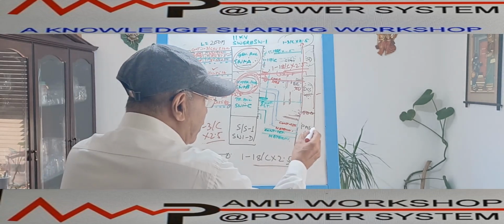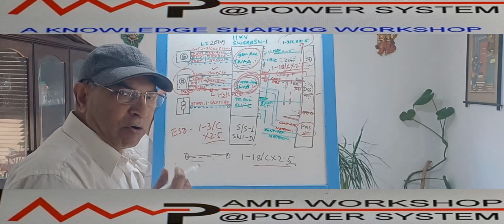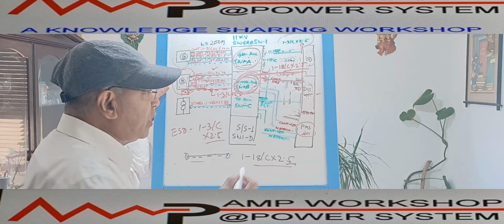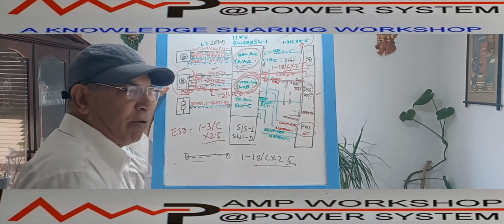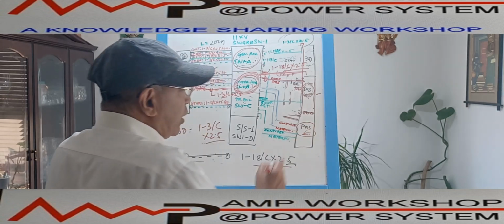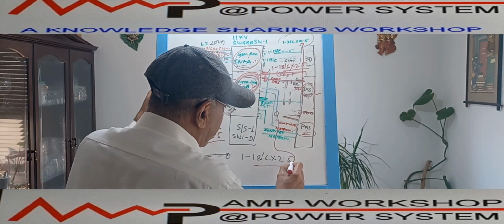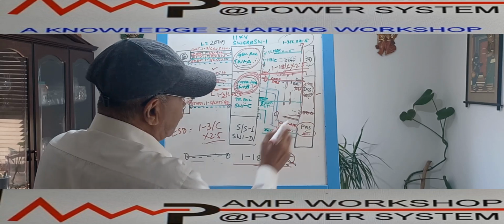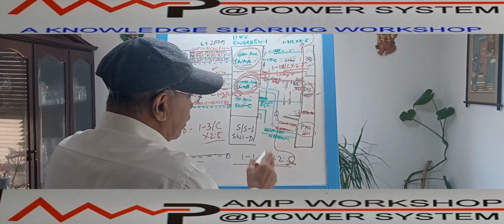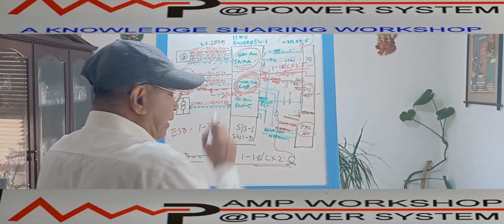Similarly, in the PMS also, we want to control this circuit breaker like the generator panel. So in the PMS there will be a control cable which will control the circuit breaker on and off, as well as monitor the various parameters of this panel as required, breaker on, breaker off, whatever status we are monitoring over here. So this is also another 18-core cable. This is the cable we have shown over here. This is the 18-core 2.5 square millimeter cable, which is led from the switchgear panel, motor panel, to the PMS to monitor the various breaker statuses as well as control the panel.